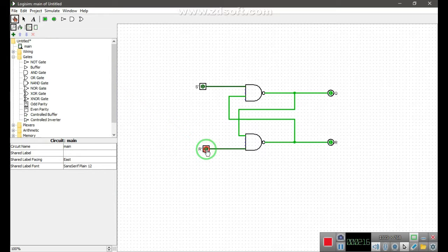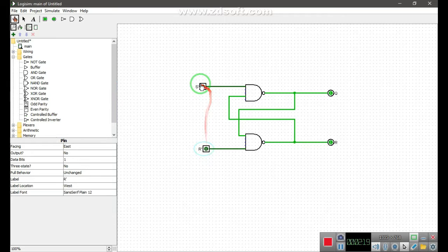As gate X has one of its inputs at logic 0, its output must equal logic level 1. Output is fed back to input capital B, so both inputs to NAND gate Y are at logic 1. Therefore Q equals 0.